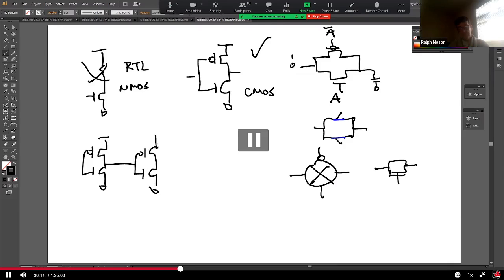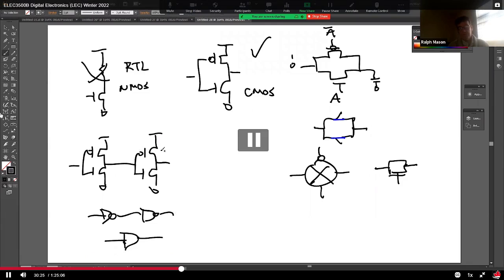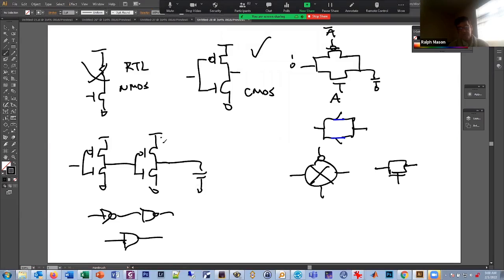And a very important difference here. It's a good question. So this is like an inverter, and then we say, oh, let's just call it a buffer, no inversion, right? But with this thing, say we have a capacitance here, it's driving current onto that capacitance, or it's sinking current from that capacitance. The transistor is driving it to the power supply.